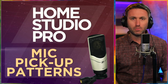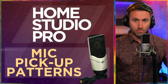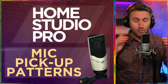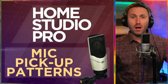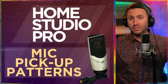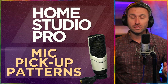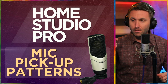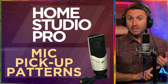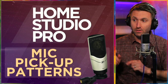Hopefully some of that made sense. Hopefully you got some good examples there of how the pickup pattern really does affect the microphone's performance in a room. Now, I've also done this entire video in an acoustically treated room, so think about that. I was playing crowd noise, but think if your problem was echoes and reverberations, that's what you're cutting down on. Really you're fighting your own space sometimes in how it sounds. And that's why the right pickup pattern is important to your microphone. So know what your mic is capable of, the different options it has, or its limitations in terms of pickup patterns.